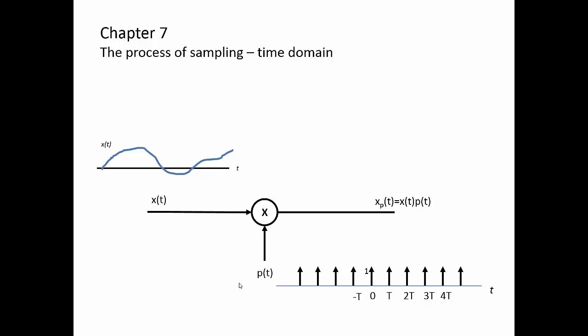We began the chapter talking about sampling from the time domain perspective, and how when we do sampling, we're looking at the values of our signal every T units, and from there we have a sampled time spectrum, which is our infinite pulse train, but now the area of each impulse is the amplitude of our time signal at those sampled time values. We're now going to look at this time signal, and from the time domain perspective, consider how we can reconstruct our original time signal.